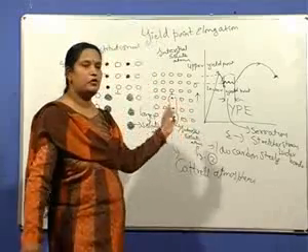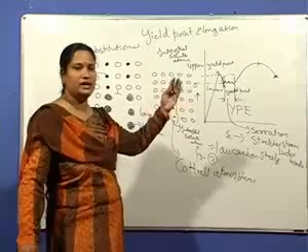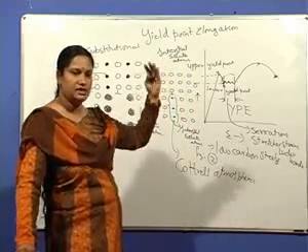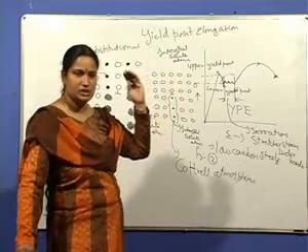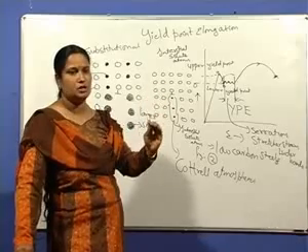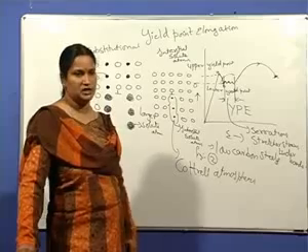Here, for the case of normal materials, in the normal stress strain curve, beyond the yield point, the curve increases because of strain hardening. The curve rises because of strain hardening, reaches the ultimate load, and then the curve drops down. That is, the stress drops down. So there is a fall in the curve and the material undergoes fracture.